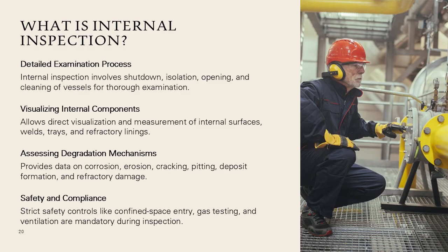Internal inspection is the most detailed form of equipment examination and requires shutdown, isolation, opening, and cleaning of the vessel or piping system. This slide explains that internal inspection allows direct visualization and measurement of internal surfaces, welds, trays, internals, baffles, refractory linings, and other features not accessible externally.